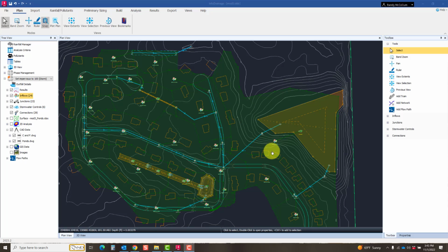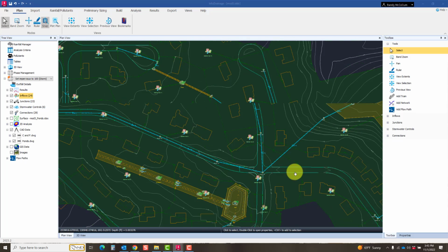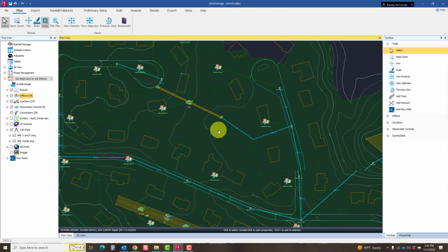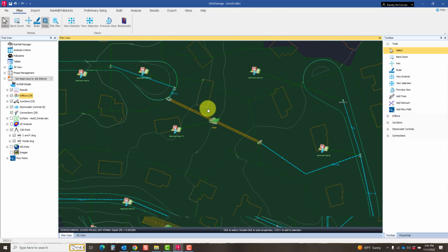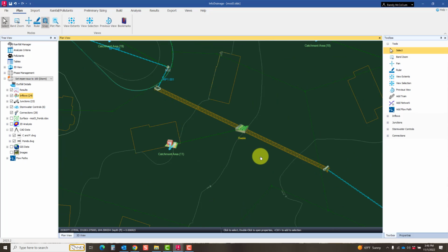You can still see the pond, although after the change is made, I have considerably larger area. All of the green areas, again, are subbasins. All these orange areas are some sort of pond or structure. So you can see I have a number of them now. And I've taken advantage of the natural terrain and placed in, instead of using traditional pipes, placed in swales.